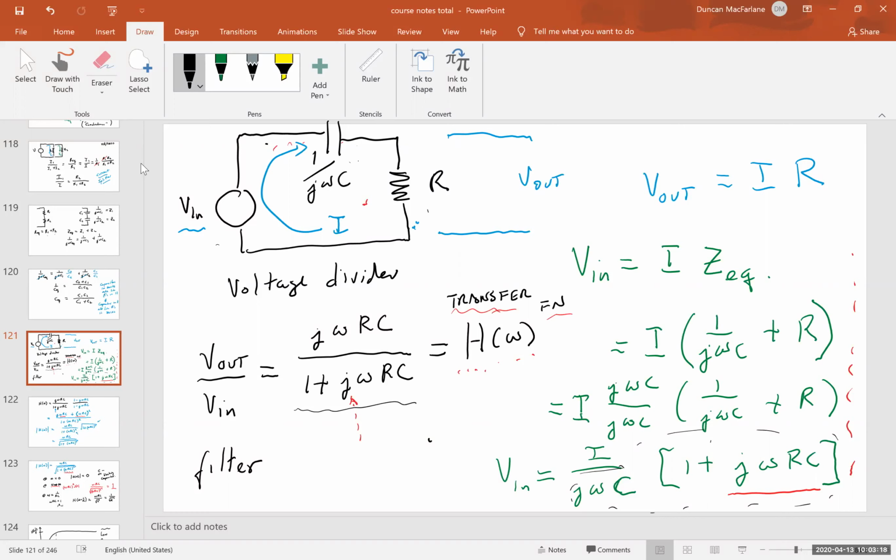We know that the capacitor has an impedance that's inversely proportional to the frequency. So as frequency goes up, this denominator gets big and the impedance, or the presence of that capacitor, goes down. And so we looked at this as a generalized voltage divider. We went through exactly the steps that we had with the two resistors there.